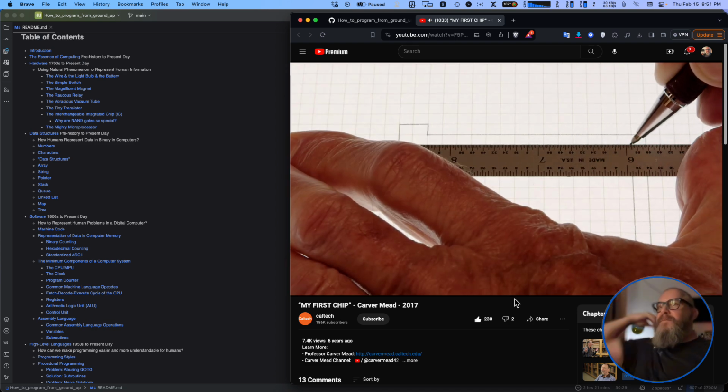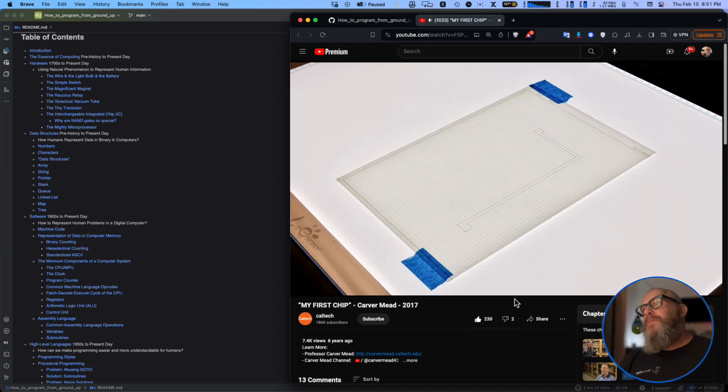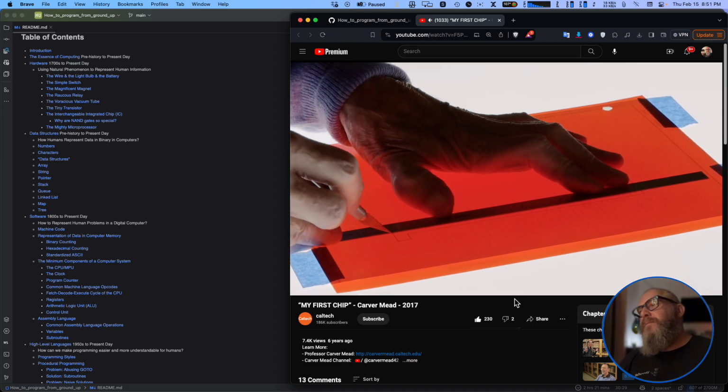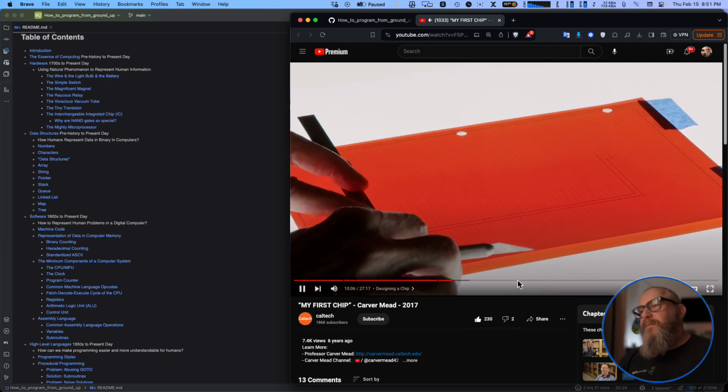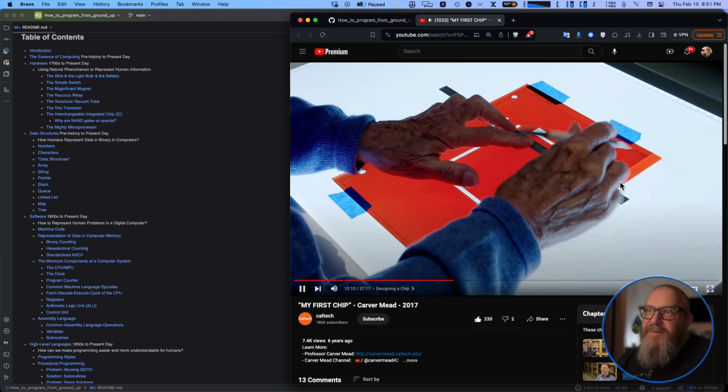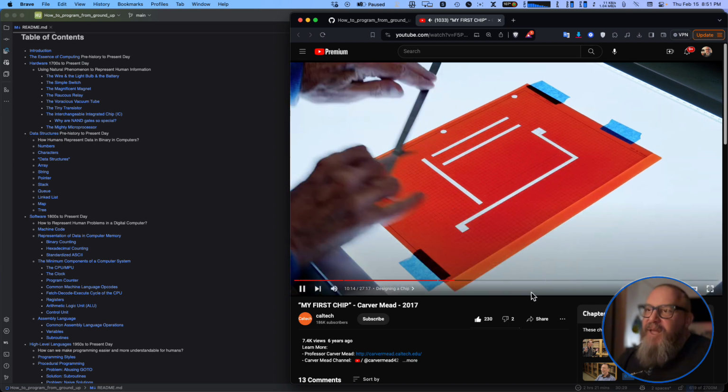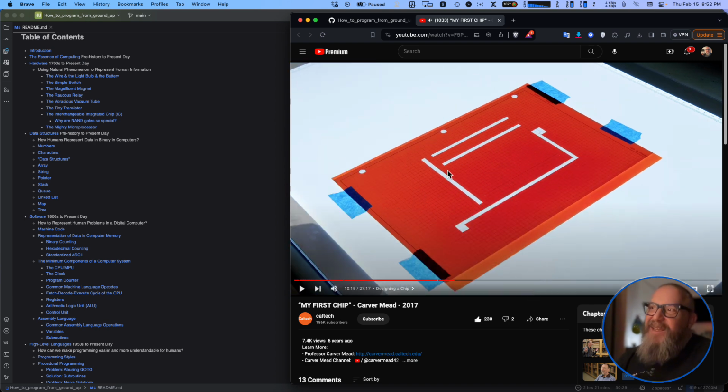Then that piece of Mylar was put on a light table, and on top of it was put a thing called rubylith. Let's say there was a stripe of the layer. They had to cut on both sides of the stripe and on the ends. So these are the wires. They did that for every shape on that layer. After that was done, each layer was a P, and the next layer was an N, the next layer was a P, and each one of these would lay down a little segment, basically a little wire made of that P material, N material, or just neutral material.